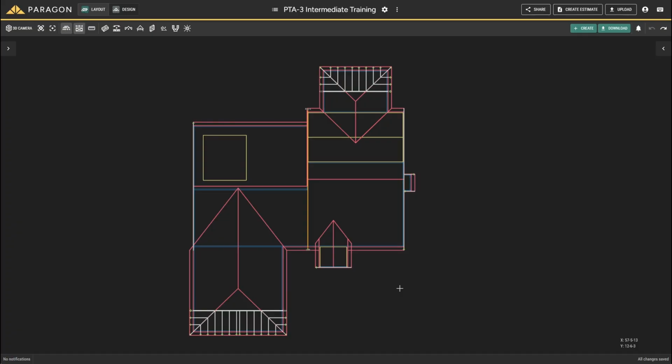In this video, we'll demonstrate how to streamline truss input using boundary-defining work lines. You'll learn how to precisely create work lines to guide truss layout, as well as how other structural elements, such as girders and existing trusses, can be used as reference boundaries during truss envelope creation.